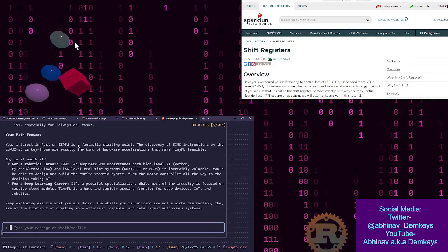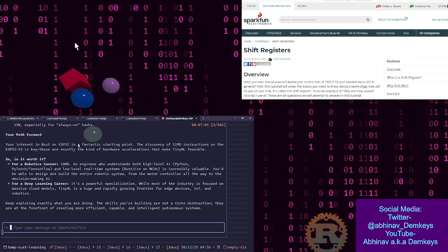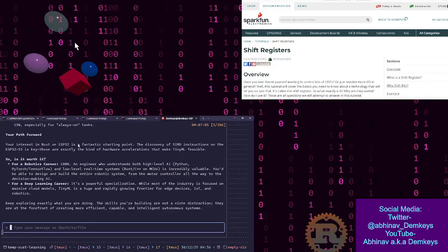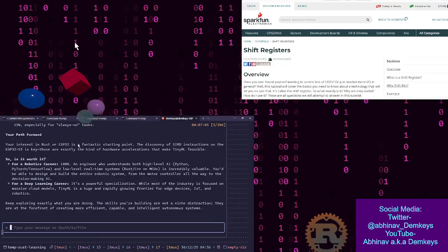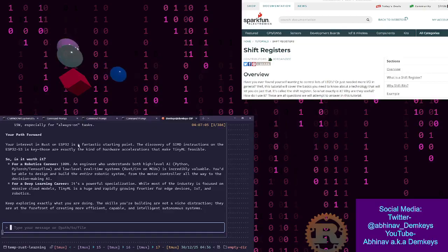The temperature sensor module contains an 8-bit sigma delta analog to digital converter and a digital to analog converter to compensate for the temperature measurement. The temperature sensor is designed primarily to measure the temperature inside the silicon. Again, exactly what I'm looking for.